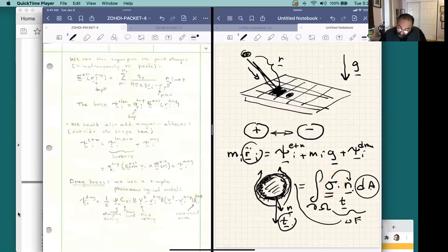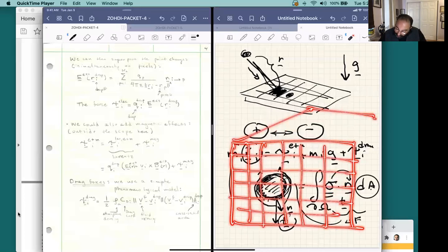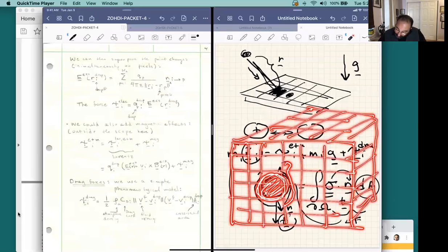And the stress, unfortunately, means that if we're thinking about how we might do it in a finite element or a finite difference or some kind of numerical scheme, typically we have to grid up the whole domain where all of this is happening. So imagine now we're putting a big box of grid points of some kind of computational tool. And we basically have to discretize this blob of material and the surrounding fluid that it's flowing through. That is a daunting problem.